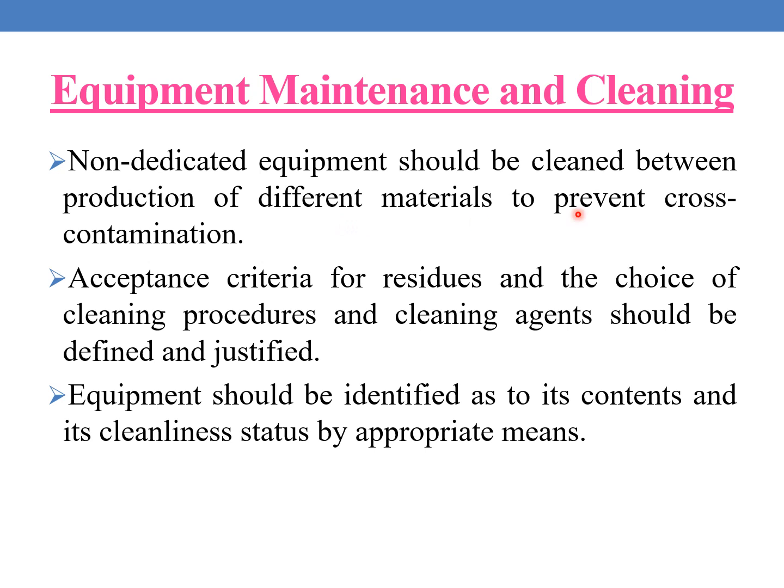Non-dedicated equipment should be cleaned between the production of different materials to prevent cross-contamination. Acceptance criteria for residues and the choice of cleaning procedures and cleaning agents should be defined and justified. Equipment should be identified as to its contents and its cleanliness status by appropriate means.